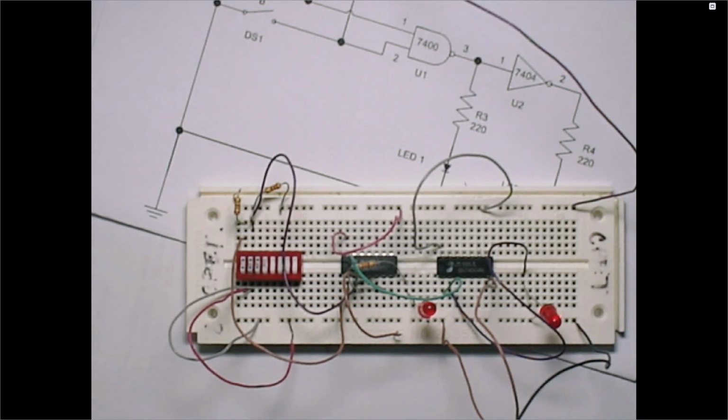Now, how do you know the circuit is working? You actually have to flip the switch, make it 1 and 0. Remember, you have two inputs, right? So you have to check 0 0, 0 1, 1 0, and 1 1, and record all the outputs. Now how many outputs do you have? 2, right? Because you have 2 LEDs. So you see if the LED is turned on, that means you have a 1 there, right?